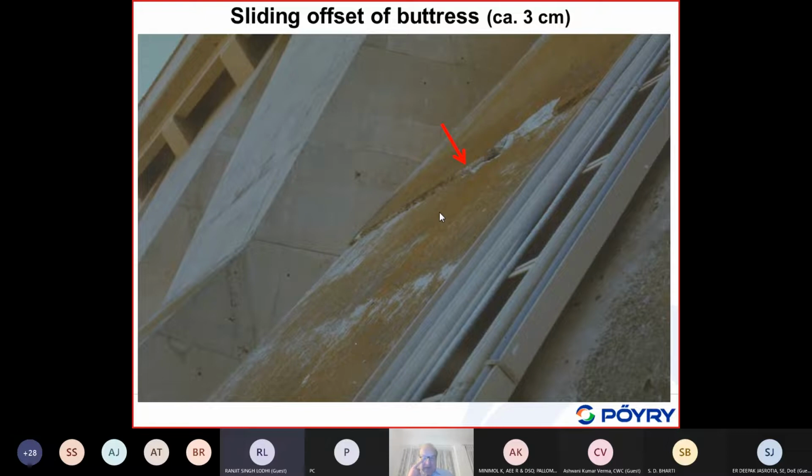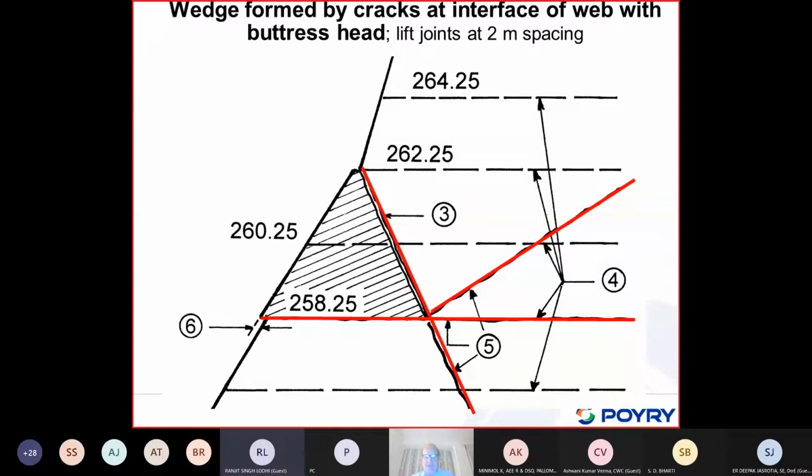But it is quite critical, because if some part is missing, is not carrying, I would say, if I just go back here, if some parts here are missing, this wedge is missing, suddenly no longer carrying. This structure here gives some more kink, and it gives unfavorable stress concentration there and redistribution of the stresses in this area.